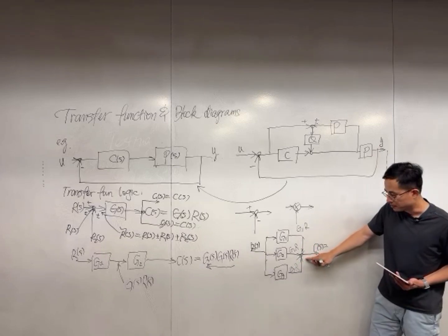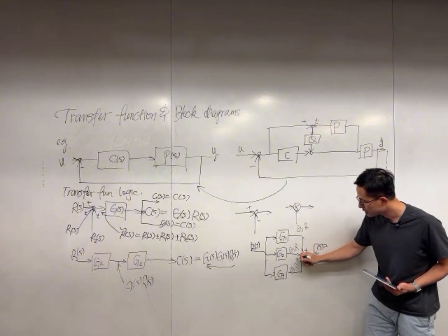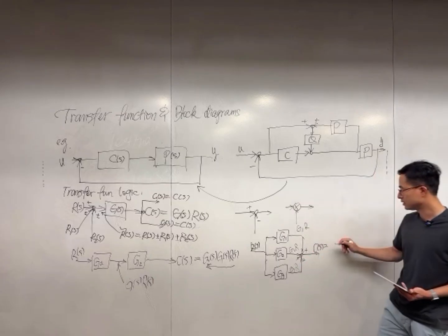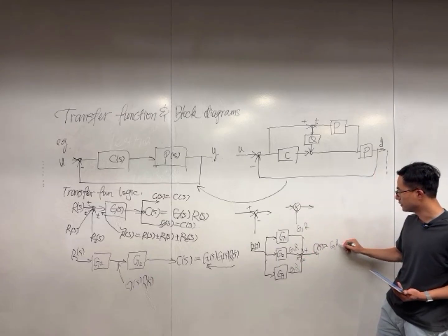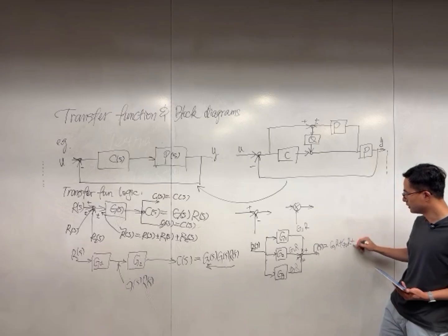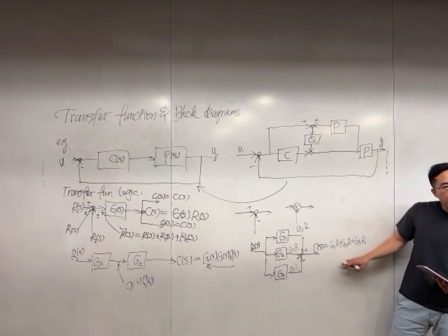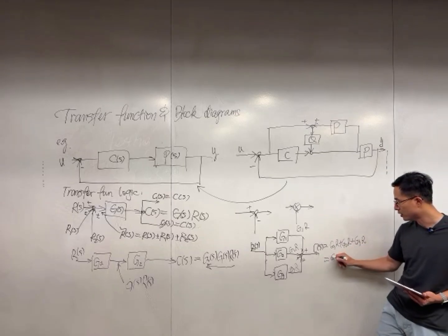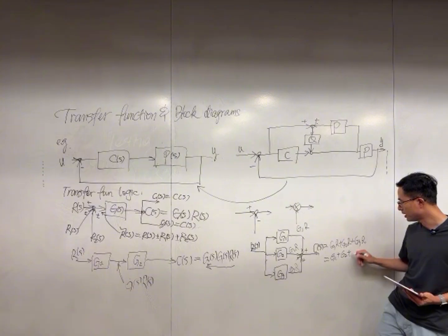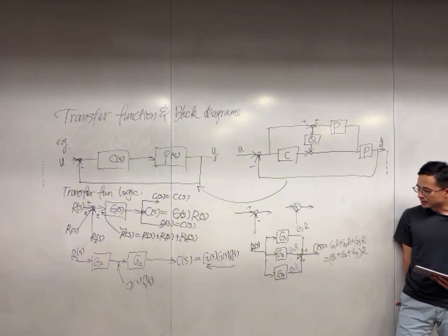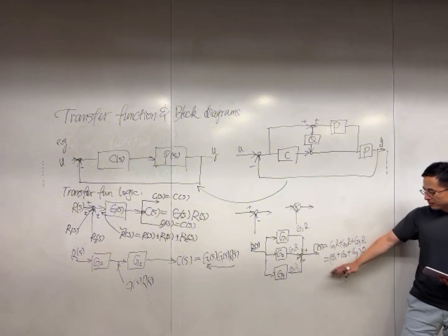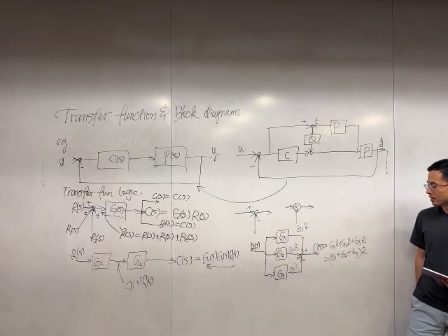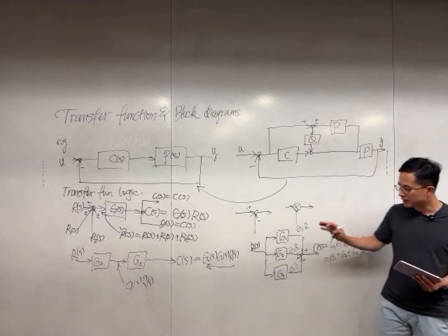And then you have a summing junction. So if I say summing junction is plus, plus, plus, then add these three together. So it's going to be G1 R, G2 R, G3 R. You can combine things, so they all have the same R. So you can write it as (G1 plus G2 plus G3) R. So that's in parallel construction. For simplicity, I have omitted the s in some of these block diagrams. So that's in series, in parallel.